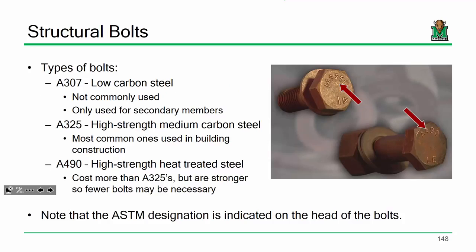I'm going to start off and let's just talk a little bit about bolts in general. Bolts are a little unlike some of the steel grades that we use in terms of availability. There are some unique little differences here and there between bolt grades, but by and large, there's really only 2 grades or 2 types of bolts that we're going to use for most civil engineering structures. We're either going to use A325 bolts or A490 bolts.